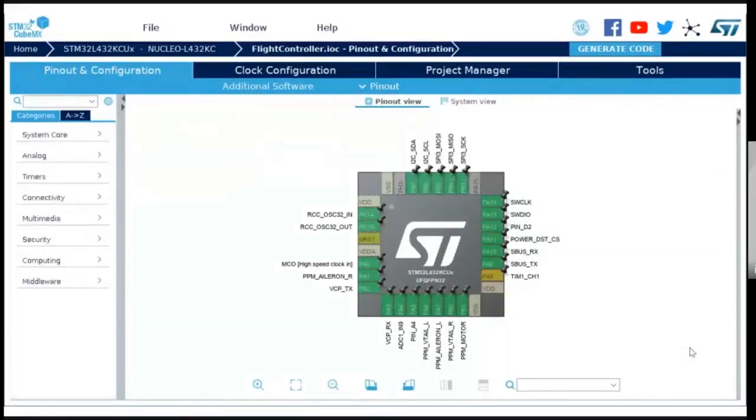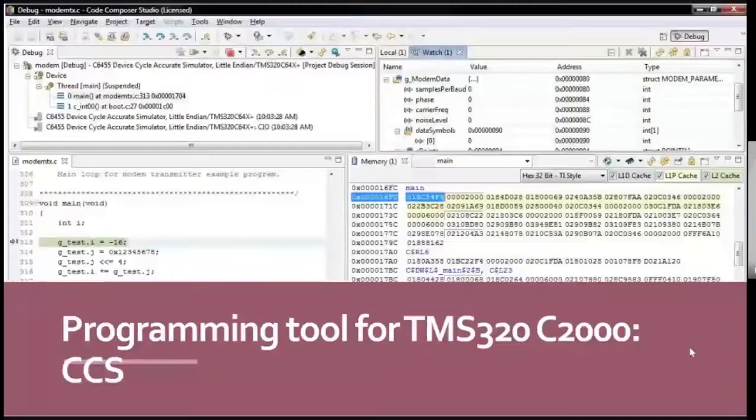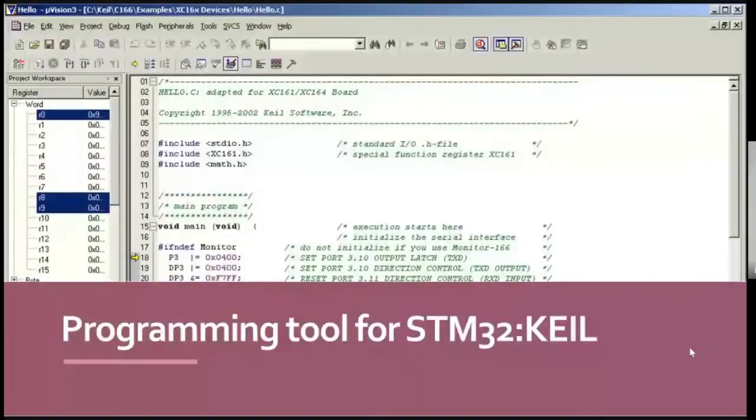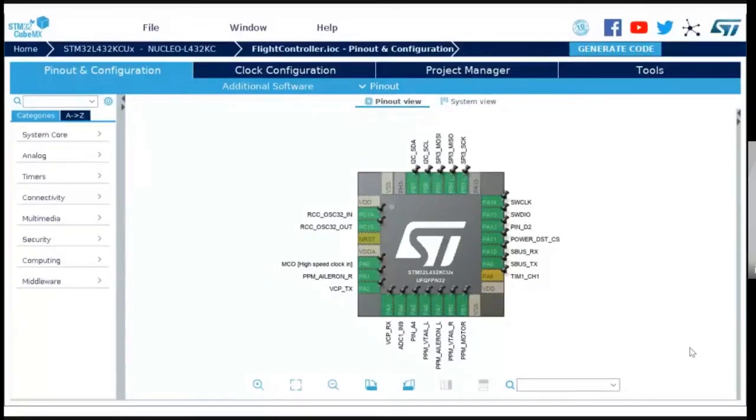Here, another feature that we have used is the next level. We have seen Arduino IDE, MPLAB IDE, Code Composer Studio and Keil. Apart from these, there is one higher level: a tool that can generate a code template. We can initialize different pins for the ST microcontroller using this code generator, known as STM CubeMX. We can choose a microcontroller, and configure every pin, timer, feature and peripheral from this application using a GUI tool. After configuring everything, it will generate a code template.